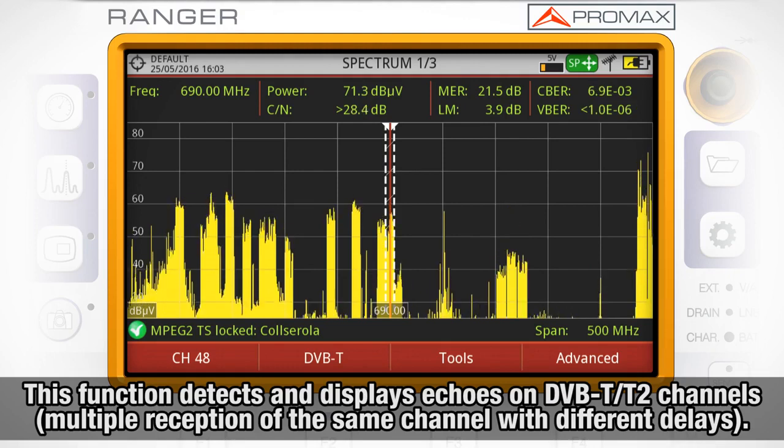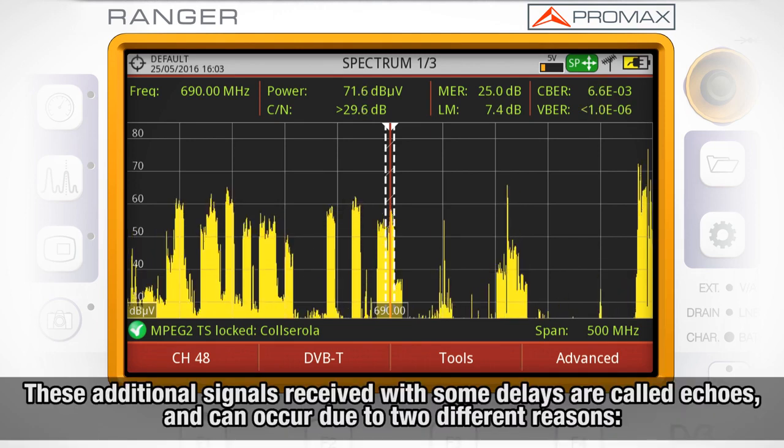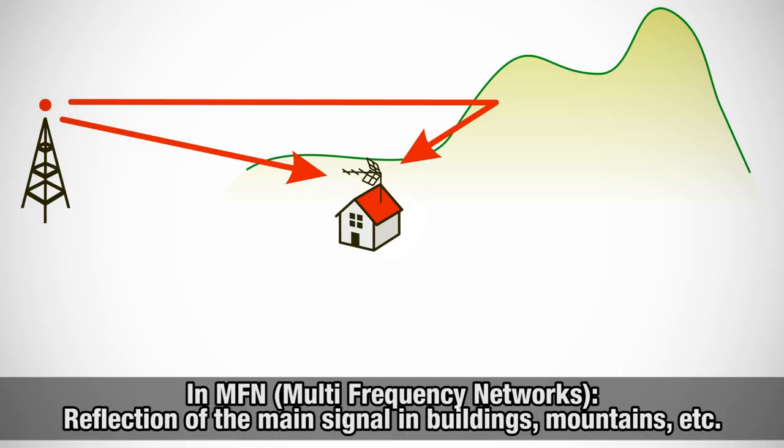The echoes function can detect and display the echoes that can occur due to the multiple reception of the same digital terrestrial DVB-T or DVB-T2 channel with different delays. These additional signals received with some delays are called echoes and can occur due to two different reasons. In multi-frequency networks, the only source and cause for the appearance of echoes is the reflection of the main signal